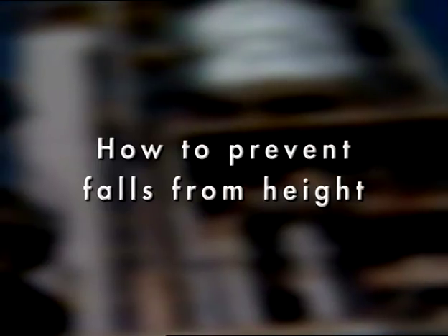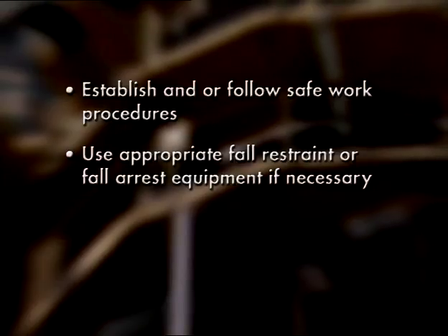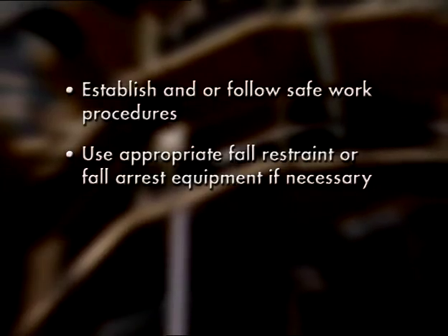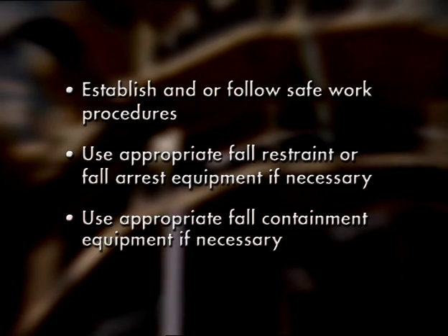Regardless of the situation that requires working at heights, there are only 3 steps that are required to ensure everyone's safety. Establish and/or follow safe work procedures. Use appropriate fall restraint or fall arrest equipment if necessary, and use appropriate fall containment equipment if necessary.